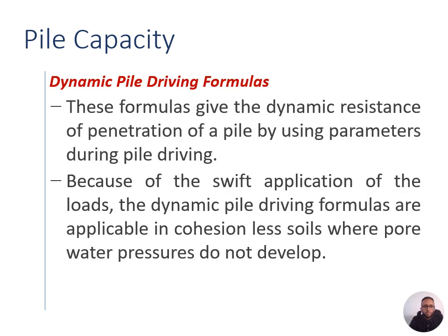Okay. The third is dynamic pile driving formulas. This method is another approach to assess pile capacity through the use of this dynamic pile formula. These formulas estimate the dynamic resistance to penetration of pile based on parameters measured during the pile driving process.